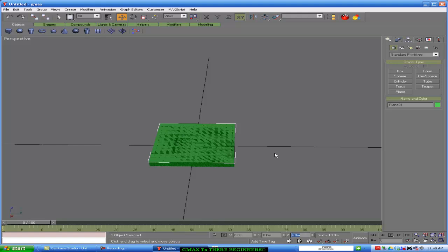Okay, now that's if we want to come up through the bottom. If you want to fall through the top, but you don't want anything coming up through the bottom, then you would reverse that. You would just simply hit the rotate tool, and in the center here you'd put a 90. I'm wrong about that. All right, let's put that back on 0. On the X, you'd put a 90. Actually, why 90? It'd be 180. That's where I'm messing up. Sorry, folks. I need a little more coffee in my system, maybe.